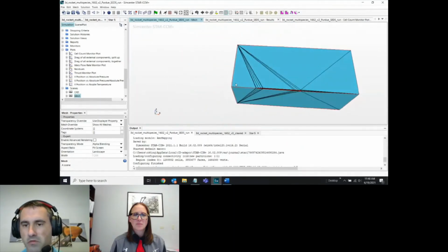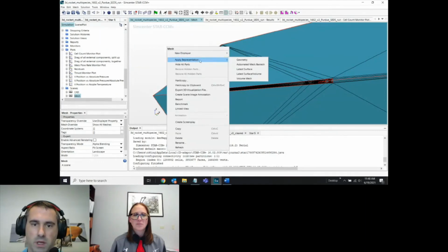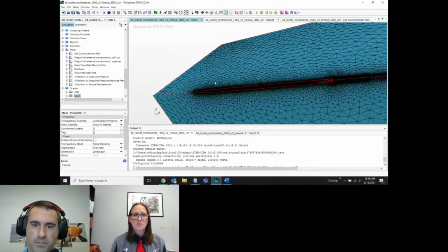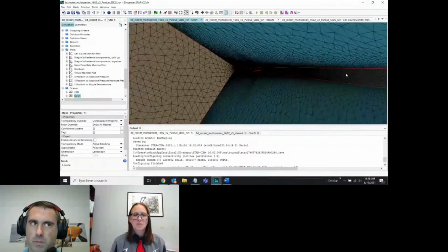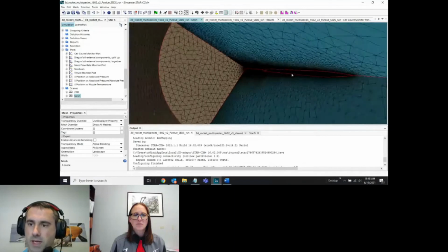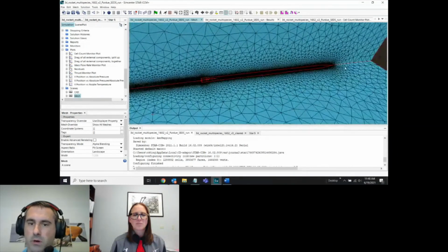Okay, so you go from CAD, which is just infinitely refinable geometry, right? And then in the process, it goes from this to a remesh surface, which is you're just essentially taking these long stretched out triangles and making them look like this, right? So you get these equilateral triangles, and this is necessary before you actually get into volumetrically meshing the geometry. So this is using all of the mesh refinements that you are applying. It's just on the surfaces though.